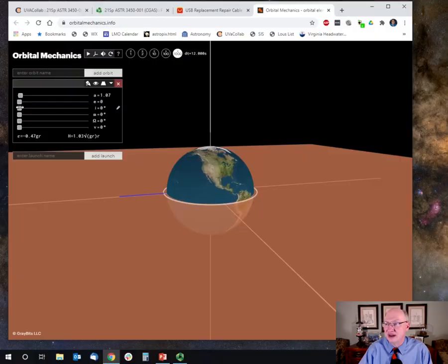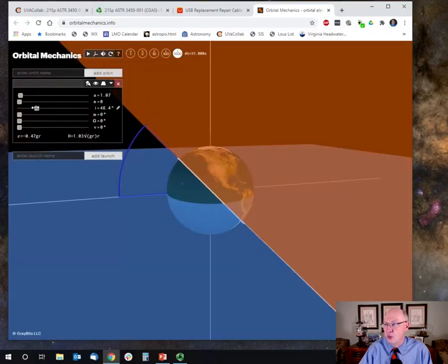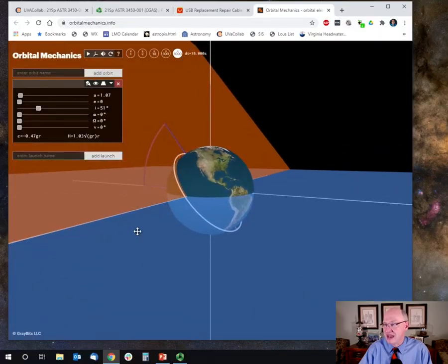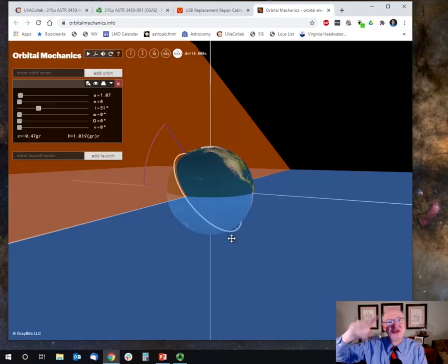The inclination of the International Space Station is about 51 degrees. So it's inclined by about 51 degrees right there. That's the orbit of the International Space Station compared to the Earth. And what you'll notice is the space station is going round and round the Earth in this orbit, and the Earth is turning underneath it. Now, the space station goes around every 93 minutes. Remember, we calculated that in the last lecture. So it takes 93 minutes to go around.